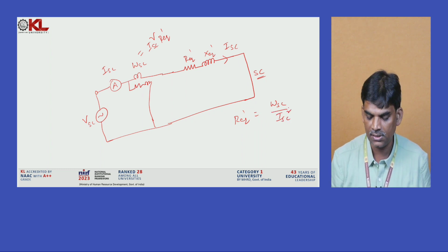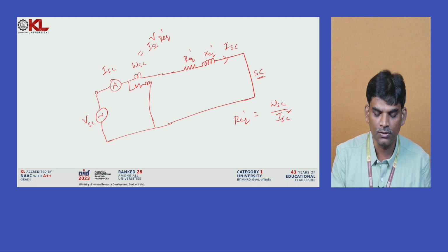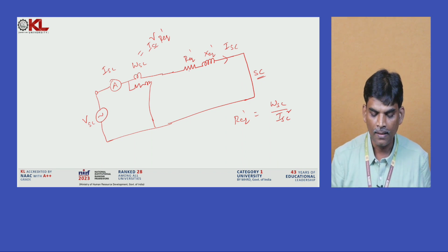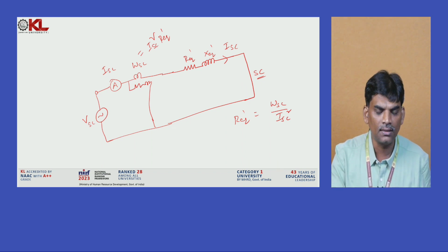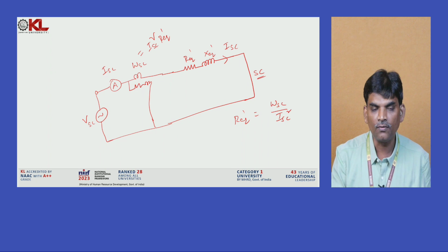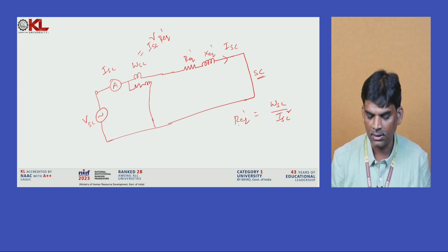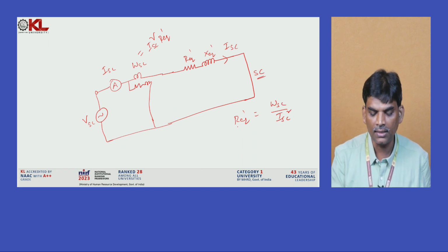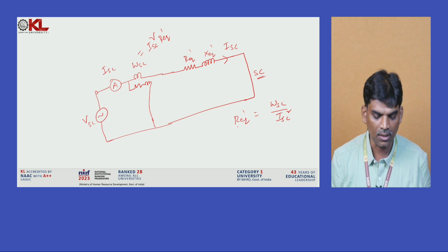So what is the power consumed in that equivalent circuit? Here, in this SC test, the wattmeter reads the copper loss of both windings. So you are finding the full load copper loss, and I am also finding the R equivalent, the winding resistance, the series equivalent resistance. The other term we need is X equivalent, but how do we calculate it?